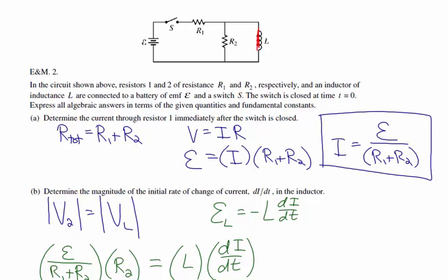And so we just have a regular wire. We can think of this as a regular wire connected here. And so that is shorting out resistor R2. You're going to have the current bypassing R2, and all we have is the battery and resistor 1 connected in series. And so our current is just going to be E divided by R1.